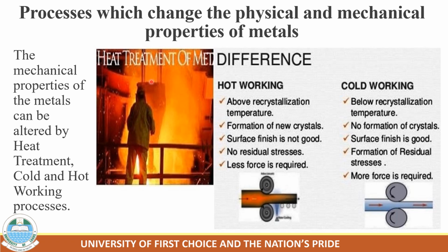And you remove it from the furnace or forge when it reaches the Austenite temperature, put it down, and let it cool down in the air. When the material cools down in such a way, the material will be softened. It will be annealed, softened for you to work with, because the microstructure inside the material will settle down conveniently.